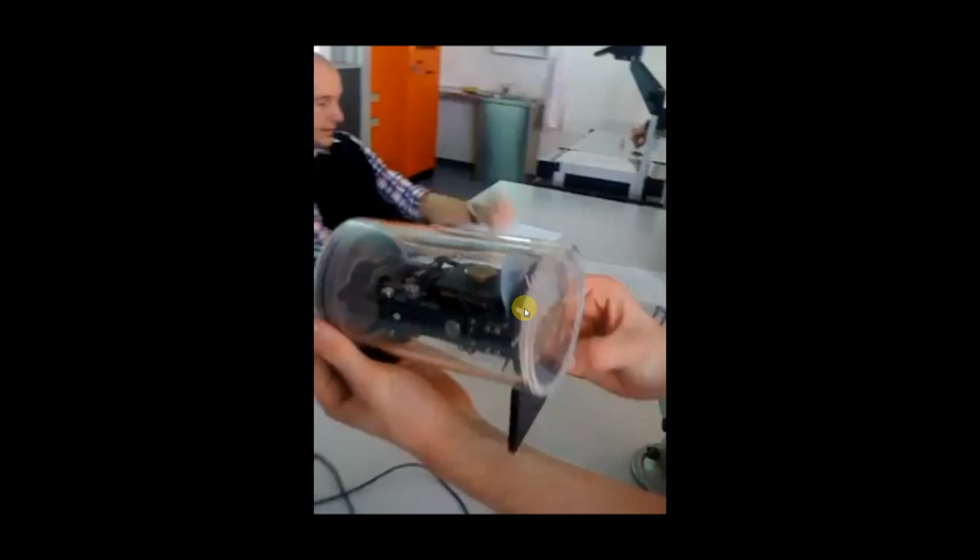So this is what the rear of the Artificial Horizon looks like. This bit is hidden away behind the instrument panel in the aircraft. So this is the front face of it. This here is the gyroscope, it's got a flywheel in there that's rotated at very, very high speed, either electric or air driven, and this is gimbaled inside this mechanism, so it is allowed to rotate freely and independently from the rest of the instrument. So just have a look at it in action.